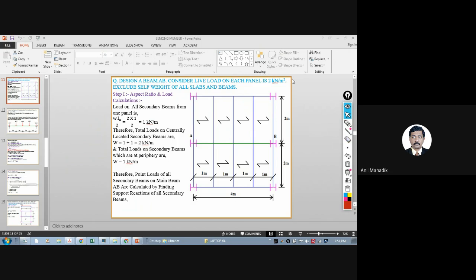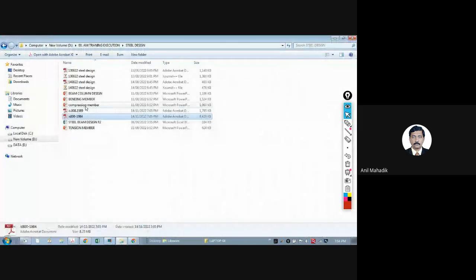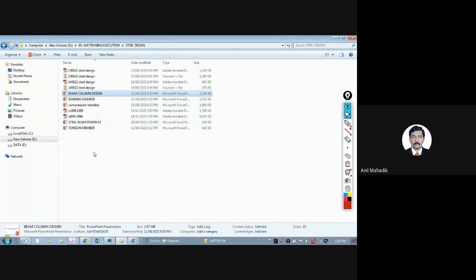Now we will switch to the next problem, which is a beam column. Only column design for axial force we learned yesterday, which is the design of a compression member, purely axially loaded. It may be a compression member like a column with axial load, or it may be trusses having compression. Now we will see how to design a beam column. Now you know what is meant by beam column. The beam column is nothing but a member carrying bending moment and axial force.